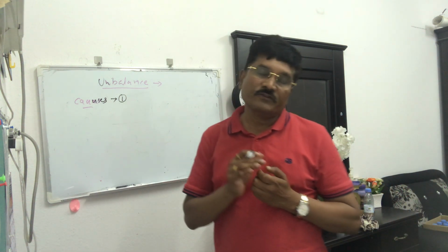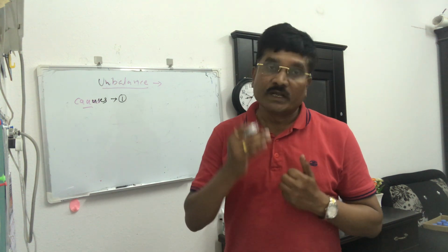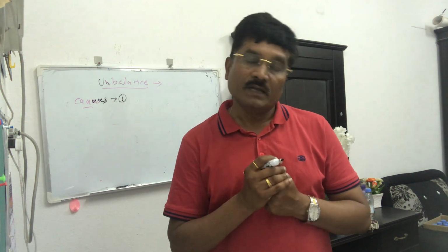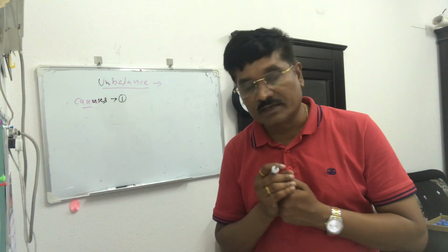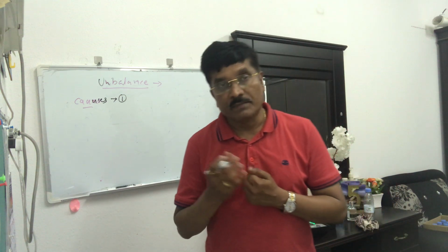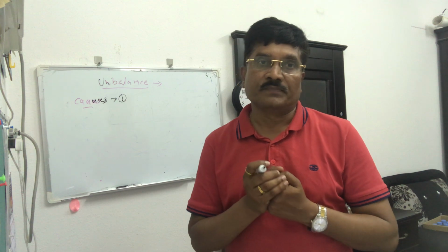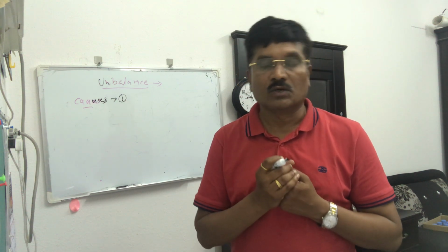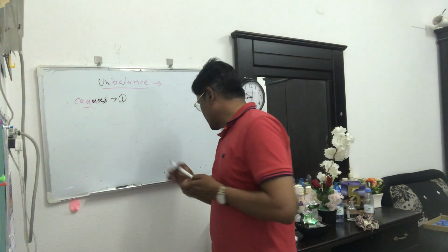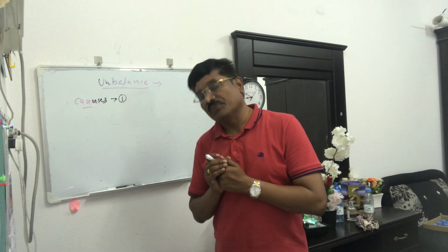Then what are the effects? As I said, it creates high vibration definitely, and due to that high vibration it damages bearings frequently, damages the seal, a very important and delicate part in the rotary machines. Then maybe damages coupling, and many other effects happen in the rotor due to this unbalanced criteria. Now we'll see what are the types which we have to face in a refinery.